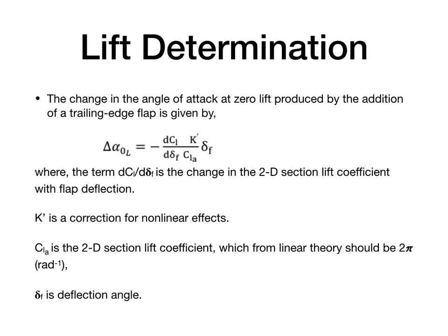It involves determining the changes in maximum lift coefficient, zero lift angle of attack, and stall angle that result from these passive lift devices. Additionally, the added drag due to the enhanced lift configuration is calculated so that it can be compared to the empirical value used in the takeoff and landing analysis.